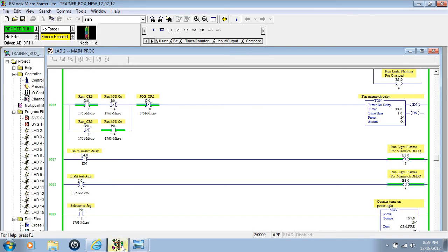And if I go back to the PLC ladder logic, if I shut this off, I'm going to actually push in this MS contactor right now, which would be a not normal function. And this would simulate that this contactor froze shut and never released. Well, you'll see, now this is true because it's highlighted, that's true because it's highlighted, that stayed true. And this timer started timing. After 2 seconds, it went done and latched this fault.